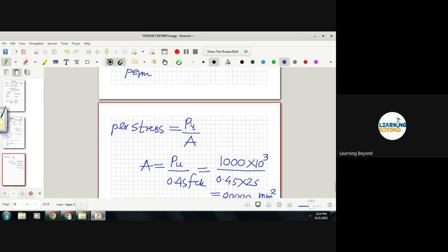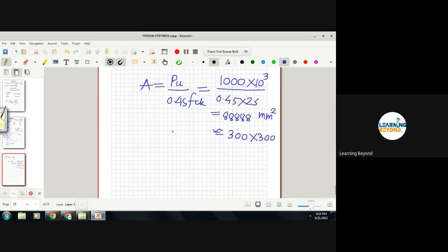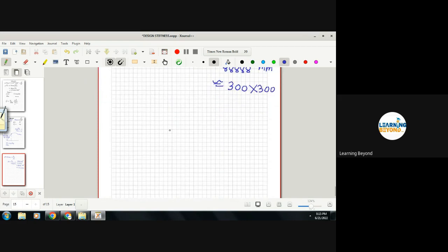You should know the force, and then you know the permissible stress. You can calculate the area of cross section of that material. So if you use this philosophy, then you can design any material in the world, provided you know the stress and strain graph along with the factor of safety. The factor of safety is generally different for different materials.